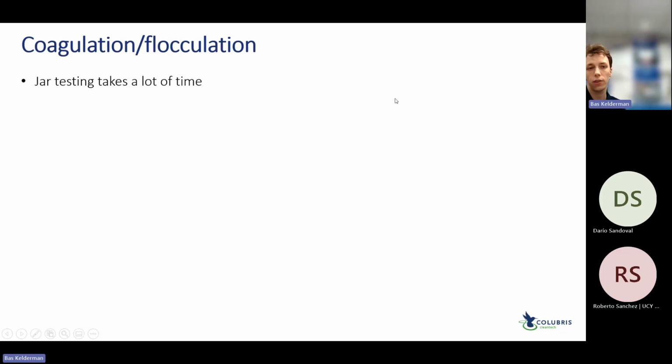Yeah, as I was saying, for jar testing, to do that on a particular bit of wastewater, it takes you some time to do that. It's not an instant measurement. You have to perform the actual jar test and make your determination based on that. And it only reflects what the correct dosage is for that little bit of water that you're testing right now.